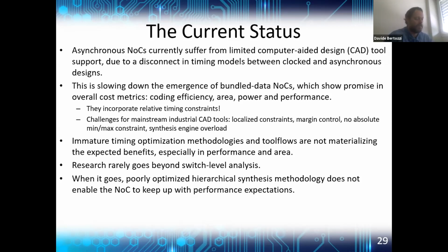These are serious issues. The currently immature timing optimization methodologies and tool flows for bundled data NoCs are preventing them from materializing the expected benefits, especially the performance benefits and the area benefits, while for power benefits, we are already there. There are bundled data switches that yield impressive power savings with respect to synchronous counterparts, for example, but they end up degrading performance and area. That's not good news. At the same time, research is typically limited to small-scale systems, switches in the best case, not networks as a whole.